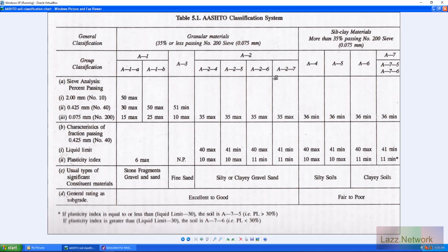So it doesn't matter what other requirements you have on your sieves at that point. Technically, if you're just doing sands with silt or silty sands, if you have anything above 10%, it's going to start at least at an A24, depending on your Atterberg, and then it just gets more and more as you go. This one covers your liquid limit and your plastic index. No matter what, if you do an Atterberg, you're still going to do your liquid limit and your plastic limit, but it doesn't care what your plastic limit is.